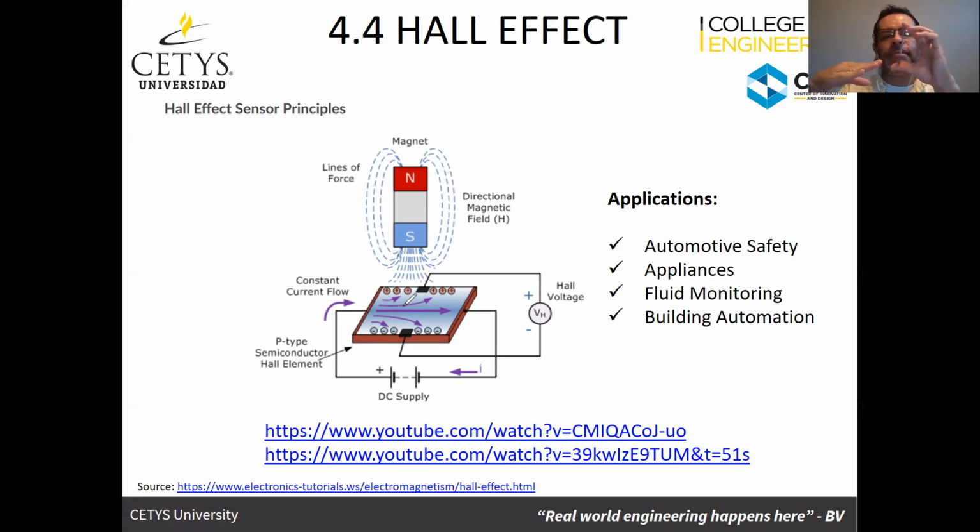And so imagine that now I have a certain flow that's going through here. And if the flow is larger, then there's going to be a diaphragm that's going to move. So somehow there's going to be a movement in the film or the diaphragm. That movement, again, is a change in the interactions with the magnetic field. And so if I can detect that movement of the diaphragm through the Hall voltage, I can relate that to the pressure of a fluid.